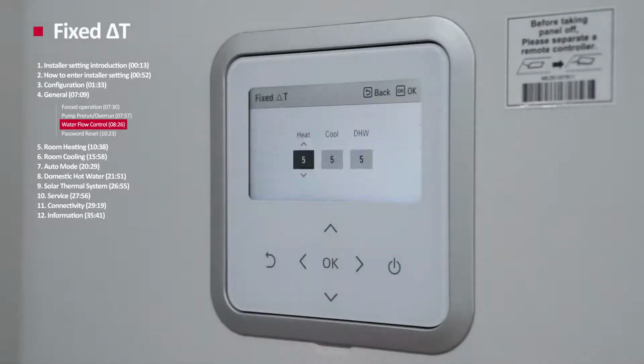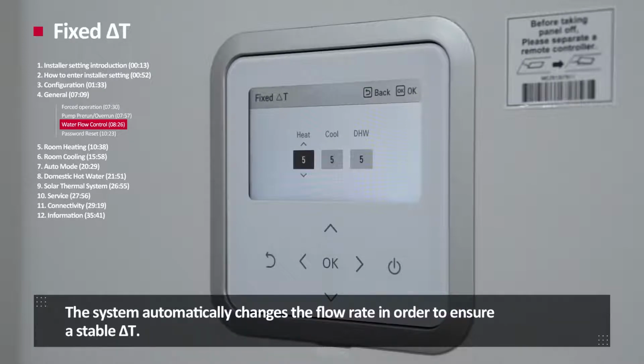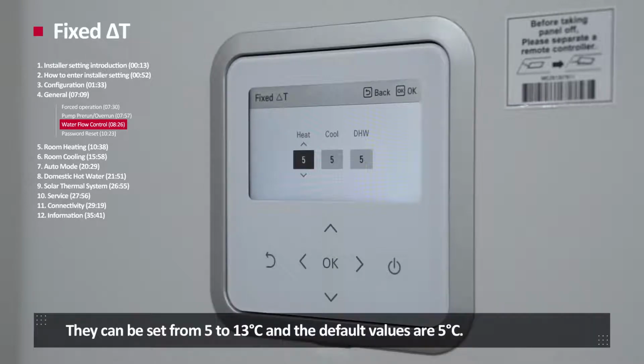Fixed delta T. Fixed delta T regulates the gap temperature between inlet and outlet water temperature for heat, cool, and DHW. The system automatically changes the flow rate in order to ensure a stable delta T. They can be set from 5 to 13 degrees Celsius, and the default value is 5 degrees Celsius.